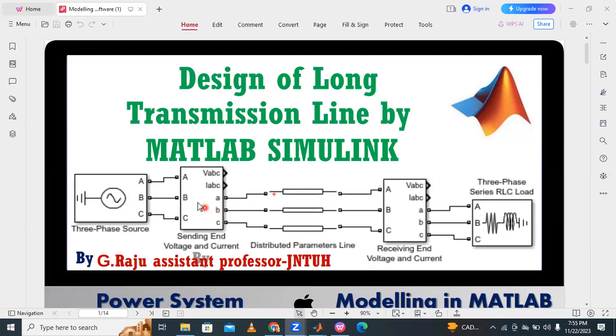And then in between the sending end side and receiving end side measurement, there is a transmission line. That is called the long transmission line. The long transmission line parameters are distributed, not lumped. So in the physical representation of the transmission line, we can't represent it as a single resistance, inductance and capacitance. All the RLC parameters are distributed, not lumped. That's why we can select this distributed parameters line from MATLAB.